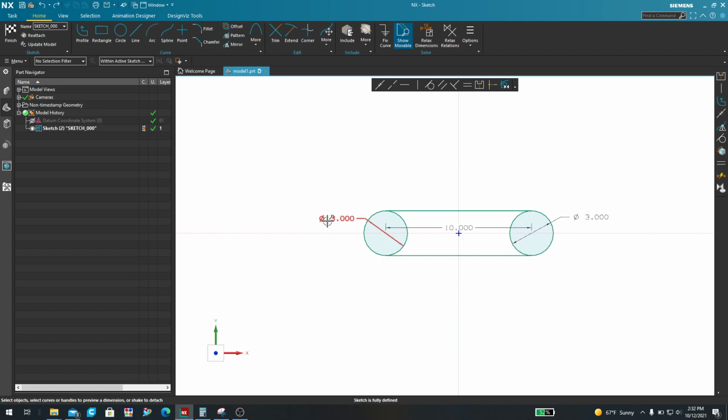And that's because in this sketcher, it's a little bit more relaxed. You don't really have to worry about over constraining certain things. If you recall, I made these two equal. But if you enter a dimension that can possibly break them, then you are telling NX that that's intentional, and it'll try its best to figure out what it is that you're trying to achieve. And that's one thing about the sketcher that's really new. It tries to solve things for you.